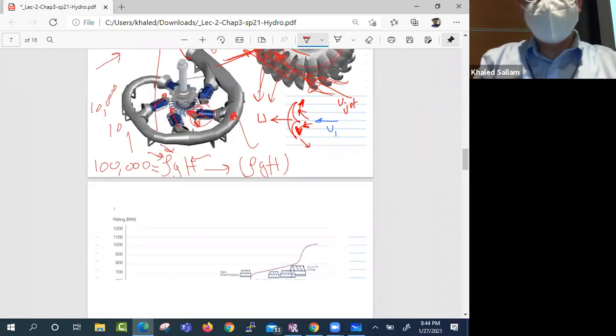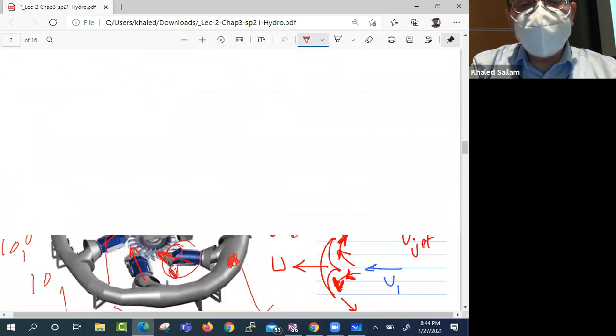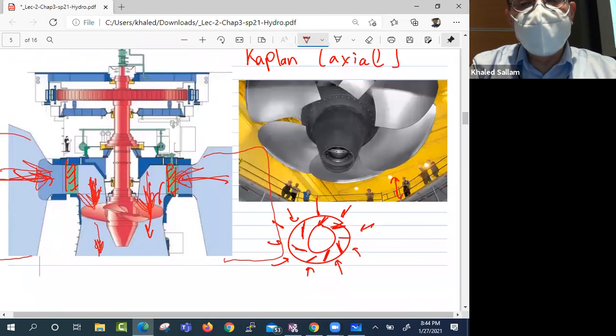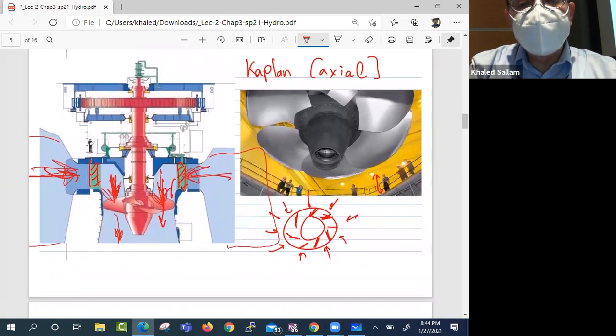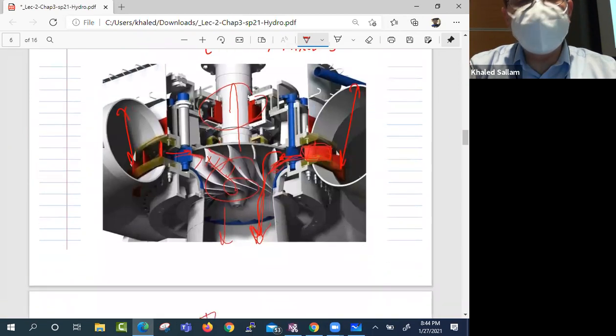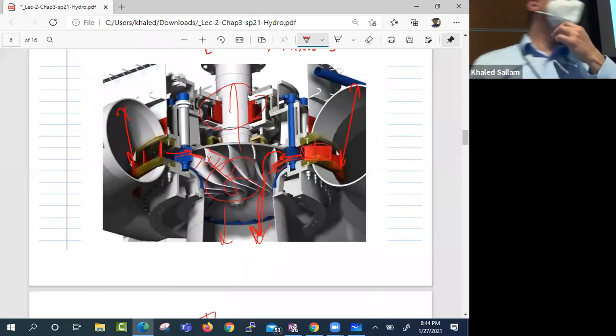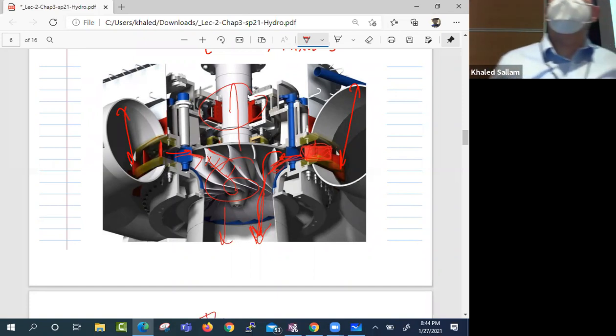All right, I want to say one more thing about this turbine plate. Which one do you think can handle higher flow rate, the axial machines or the radial machines? And the one that handles higher flow rate usually does not have that much pressure drop. So those are opposite to each other. If you really want to build very high pressure, you will have to be happy with lower flow rate, and vice versa. So which one do you think will handle higher pressure drop?